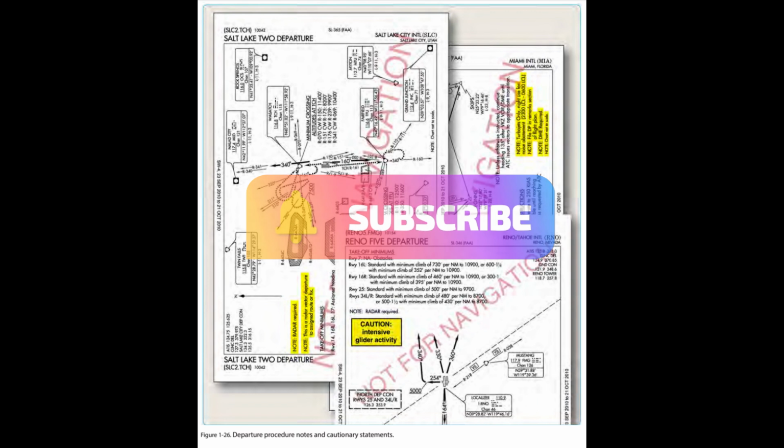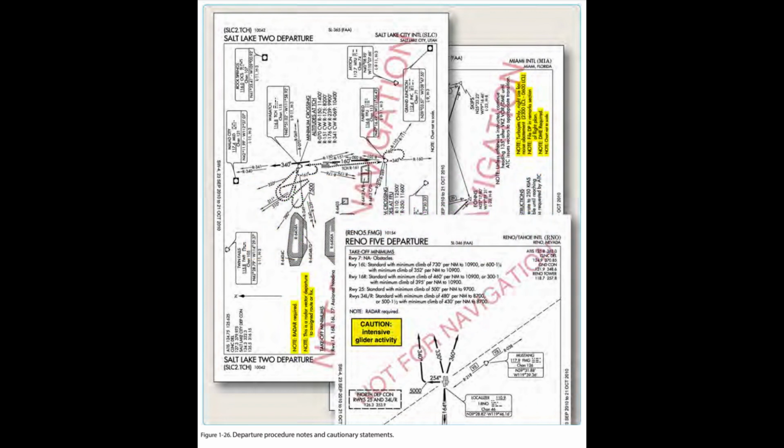These DPs may also be designed using dead reckoning navigation. Some flight management systems, FMS, are certified to fly a non-RNAV DP if the FMS unit accepts inputs from conventional avionics sources such as DME, VOR, and localizer, LOC. These inputs include radio tuning and may be applied to a navigation solution one at a time or in combination. Some FMS provide for the detection and isolation of faulty navigation information.